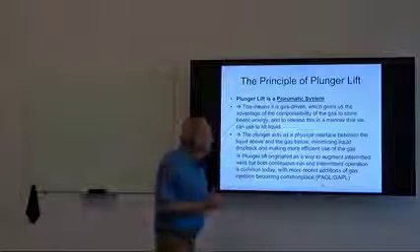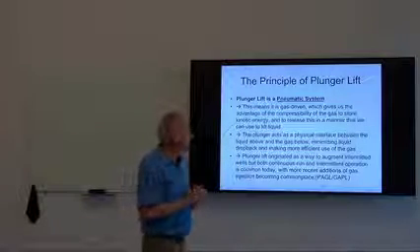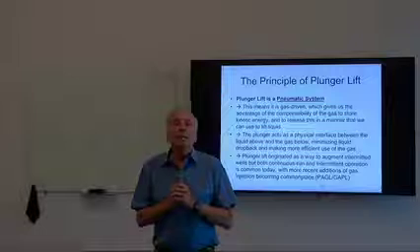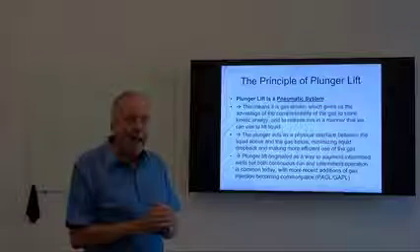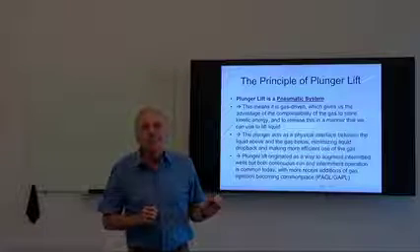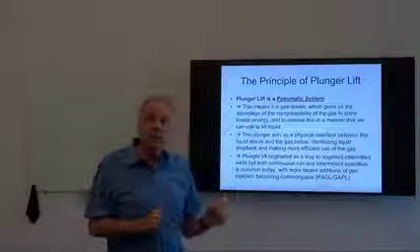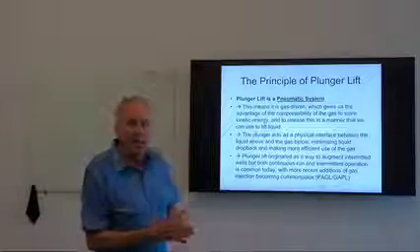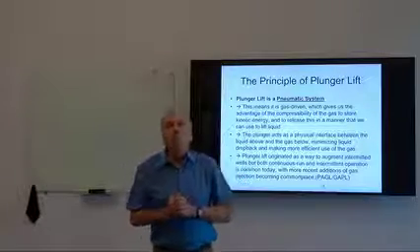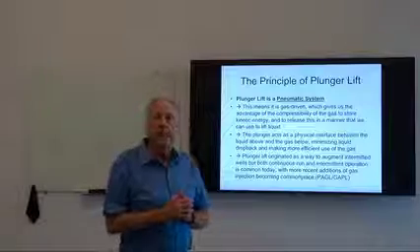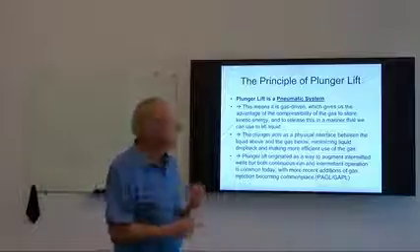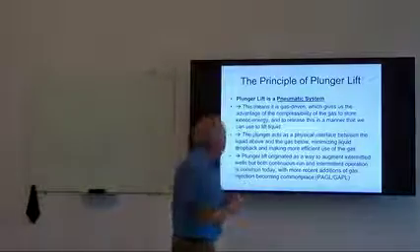Now, it's interesting to note that plunger lift originated as a way to augment intermittent wells. So unloading gas wells, if we go back 30, 40, 50 years, was often a matter of flow the well up, and as we saw in the previous illustration, until it loads, shut it in for some period of time, hours, maybe days, maybe longer, and then vent the well or flow it down line in an intermittent fashion and just let that pressure and gas flow and gas velocity carry the liquid out of the well.